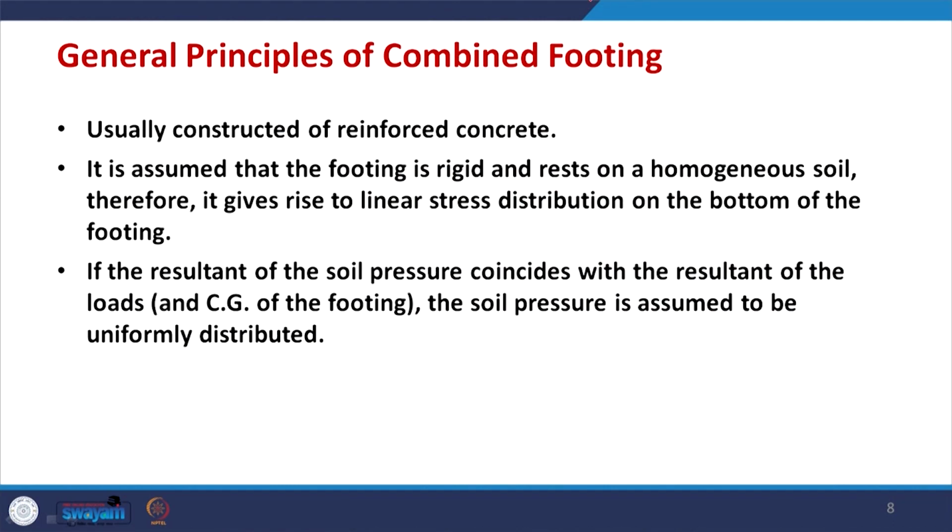Continuing with this, general principles of combined footings are listed here. Generally it is constructed of reinforced concrete. It is assumed that the footing is rigid and it rests on a homogeneous soil, and therefore it will give a linear stress distribution at the bottom of the footing.